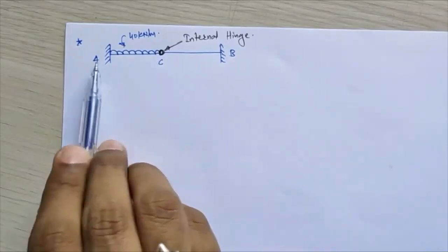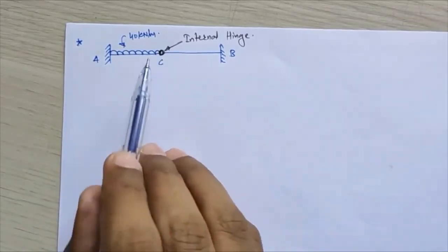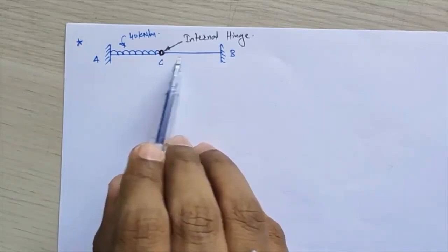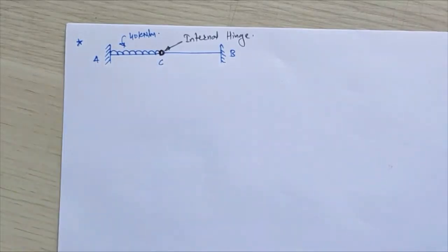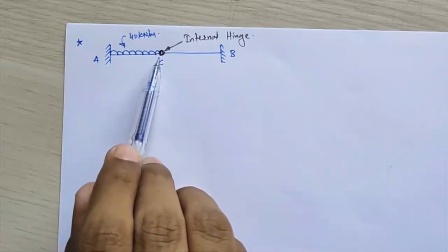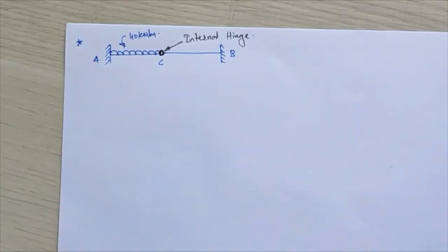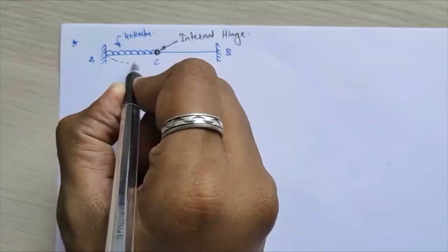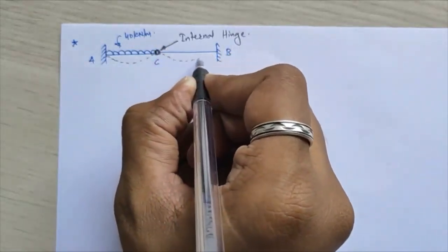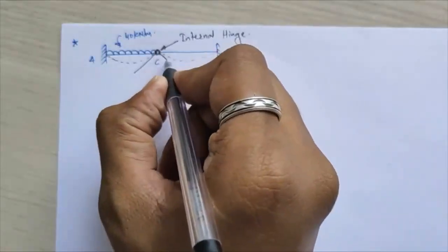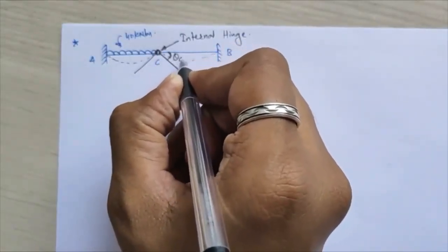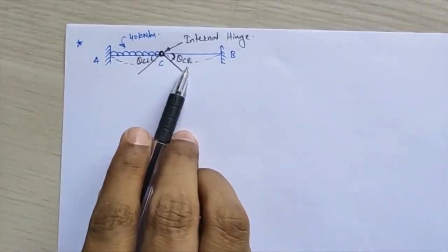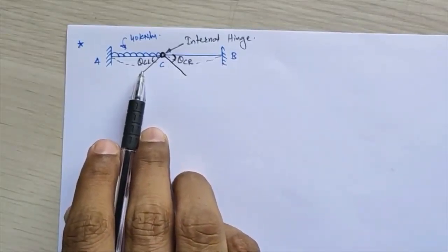Its individual moment on both the sides will be 0. That is, if I consider the moment for member CA and the moment for member CB, its individual moment will remain 0, and its slope will remain 0 again. So if you see the deflection curve of this, it will be in this way, which will produce different slopes on both the sides. Suppose this is the slope on the right hand side, and this is the slope on the left hand side. So I am writing this as theta CR and this as theta CL.